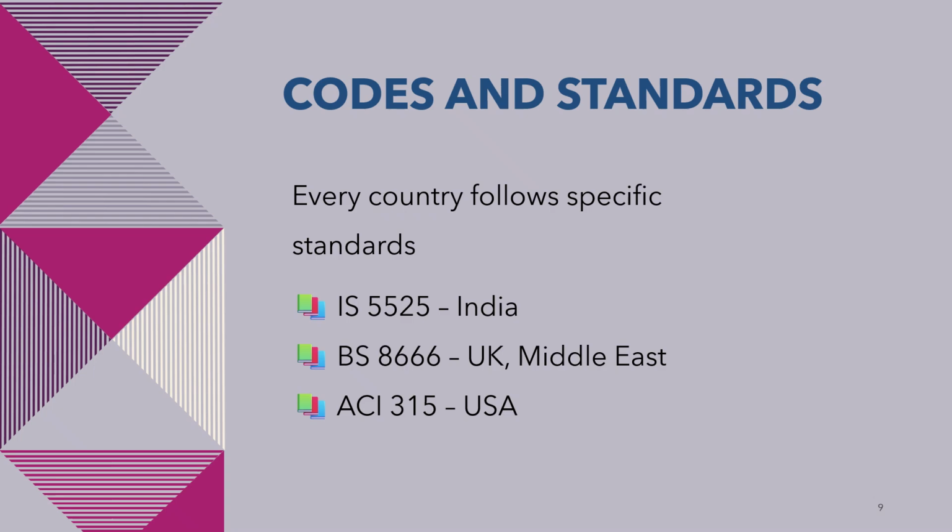IS 5525, India. In India, reinforcement detailing is commonly carried out in accordance with IS 5525, along with other relevant Indian standards. These standards provide guidelines for preparing reinforcement drawings, detailing practices, bar bending schedules, and reinforcement placement. If you're working on projects in India, it's essential to be familiar with these requirements.